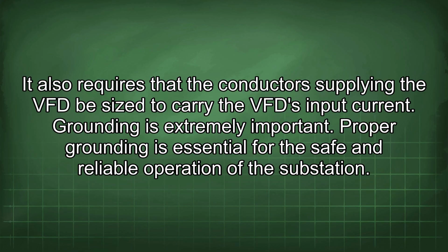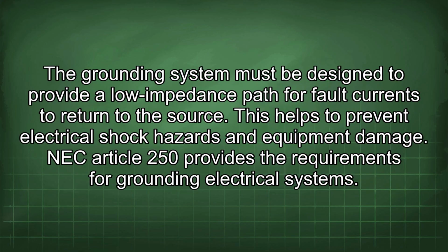Grounding is extremely important. Proper grounding is essential for the safe and reliable operation of the substation. The grounding system must be designed to provide a low impedance path for fault currents to return to the source. This helps to prevent electrical shock hazards and equipment damage.